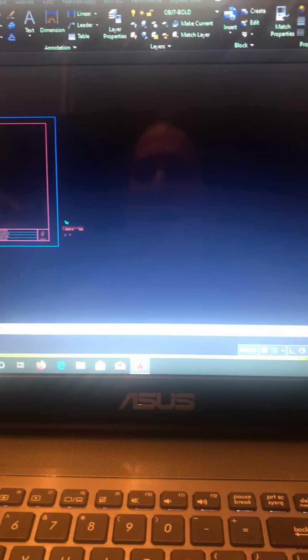The black area that you see, this is your drawing area. This is infinite, okay? The ribbon up here, this is all of your tools that you will use. Most of your tools will be on the Home tab. You do have an Annotate tab that gives you multi-line text and dimensions. You can also get to this on the Home tab. I don't usually stray from the Home tab. This has everything I need to work in AutoCAD.